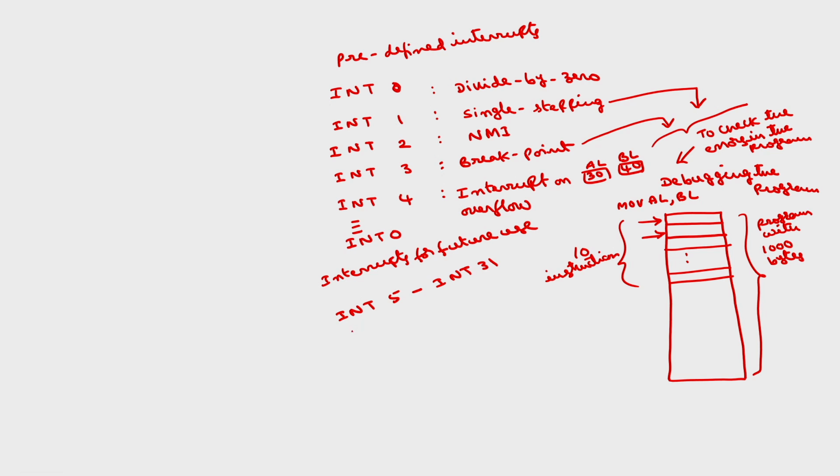And there are some interrupts which are maskable interrupts. The remaining interrupts, INT6 to INT255, can be used as maskable interrupts.